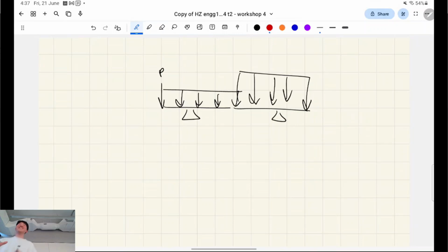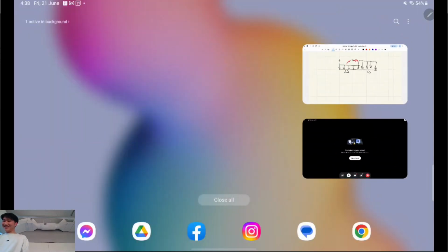In both the assignment and in the midterm, you're going to have to get familiar with the fact that the free body diagrams might have arrows pointing at distributed loads. It's going to say something like 5 kilonewtons. It's saying this arrow refers to the fact this distributed load is 5 kilonewtons. It'll say kilonewtons per meter. It's not a diagonal point load. Yeah, it's quite a confusing notation. What I do in my notes is I usually draw a squiggly line. There's no confusion if it's a squiggly line instead of an arrow. No, good point though. Please don't make that mistake in your midterm.